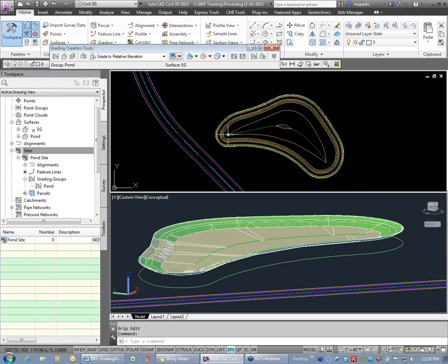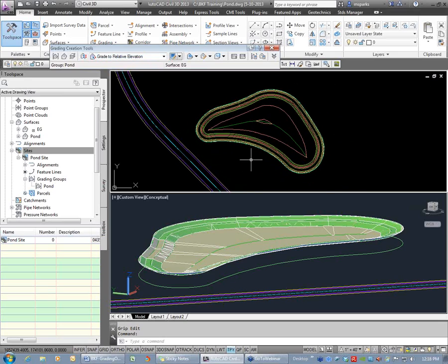Okay. All right, so we've been designing with the graded relative elevation, distance, etc. Let's say I want the outside of the pond now to go to daylight to the surface. So we're going to do some 2 steps. First thing I'm going to show you how to daylight just with a certain number for cut and fill, and I'm going to show you how to do some transitioning. Okay? So for this thing around the outside of the pond, this time I'm going to grade the surface.